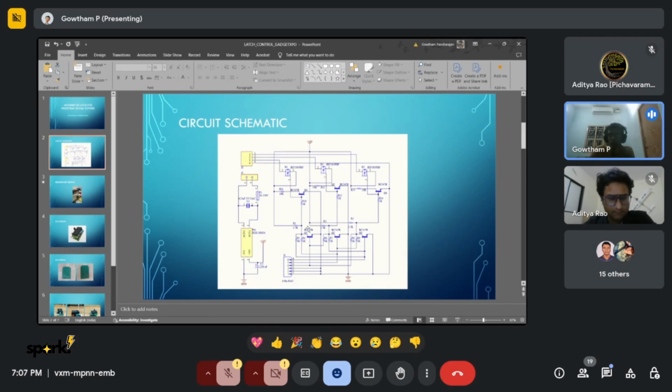So all three transistors are coupled together instead of two as in an SR latch. I've also connected the collectors of all three transistors to three MOSFETs, which in turn can be used to control any high voltage supply, something like traffic lights or industrial signal towers.